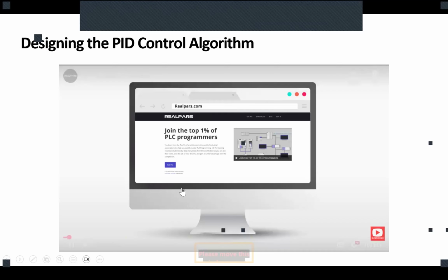As you can see, the temperature is not exactly held at the set point of 70 degrees Fahrenheit, but cycles above and below the set point. On-off control may be okay for your house, but it is not okay for industrial processes or motion control.